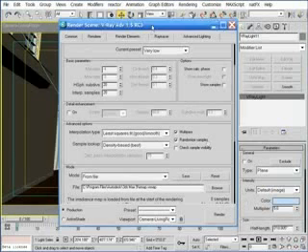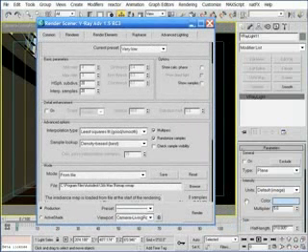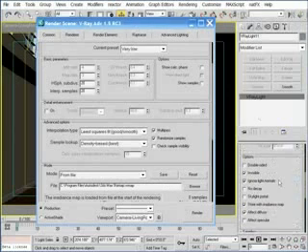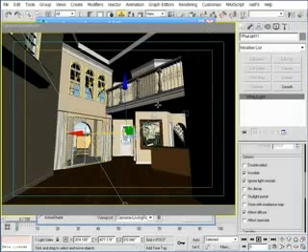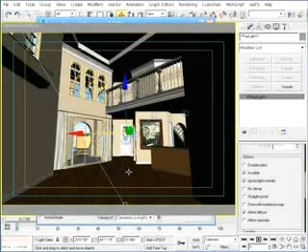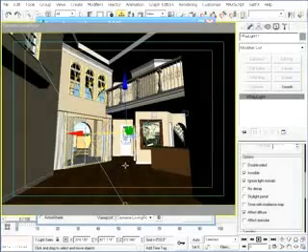This has the side effect of not allowing the light to be reflected in the rendering, because as far as VRay is concerned, the light doesn't even exist anymore. It's not going to show up because it's turned off. Yet its effect, its illumination, is still showing in the rendering because it was stored with the irradiance map. So I'll disable this option and go back to rendering in single frame mode, but I just wanted to point that out because that is one nice way to get that effect specular, that specular highlight from the light, not to appear in your final rendering.